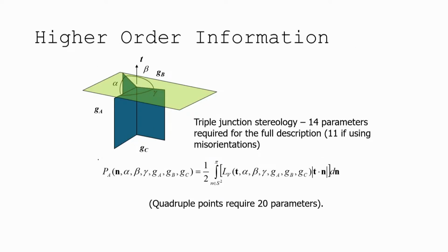Now what if we get really scary? Now we're going to talk about triple junctions, right? And I mentioned that's what we're going to collaborate on together. IIT, KGP, along with WSU, we're going to collaborate on looking at triple junctions. And so if we look at a triple junction, we have 3 orientations associated with that one triple line, right? That's where 3 grain boundaries come into coincidence with each other along a line.